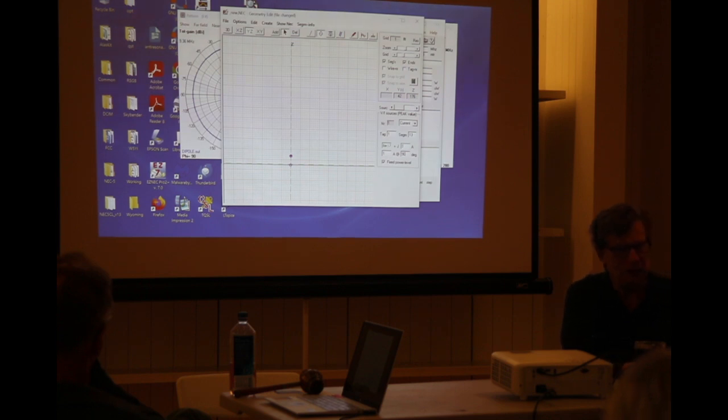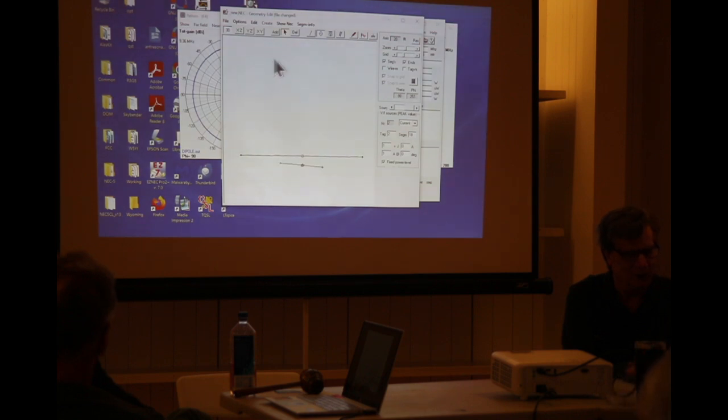Now you can express it either as imaginary numbers with a real and imaginary root, or just the amplitude and the phasing. So we have 1 ampere at 90 degrees on that feed point, and 1 ampere at 0 degrees. For a sanity check, we can go to our 3D view, make sure these aren't overlapping here. They're spaced a little further apart than I want, but we should be able to get a pretty nice circular pattern here.